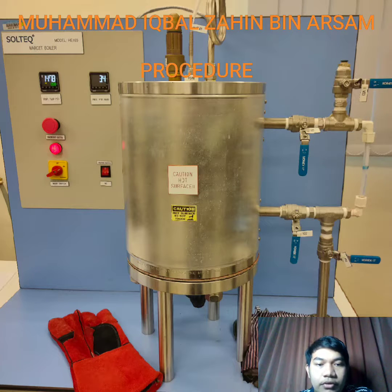This step is important to remove air from the boiler, as the accuracy of the experimental results will be significantly affected when air is present. Next, record the steam temperature and pressure when the boiler is heated until the steam pressure reaches 6.0 bar.